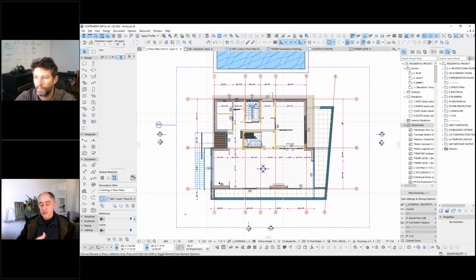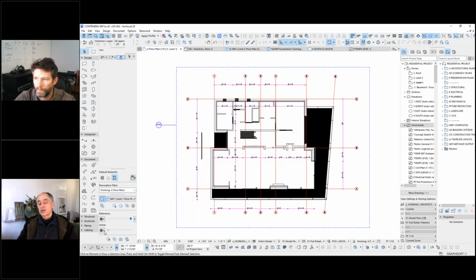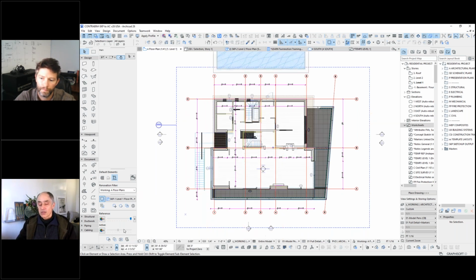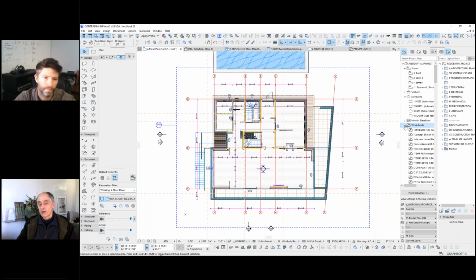Now, John, you've just given two different ways to simplify it. One is taking something that is a live 3D view and just making a copy of it in a worksheet, so it's just 2D, it's just lines. So now it's much easier for it to throw the lines as a background, as a trace. In addition, you talked about taking the lines and putting them on the ArchiCAD layer. Why? Because with the ArchiCAD layer, anything that's on there doesn't disappear. It's always turned on.